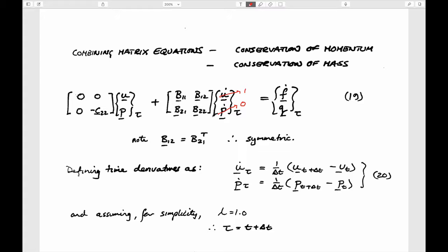And if you do that, then what that physically gives you is a reasonable interpretation of what these matrices are meaning in terms of process. And so the process would be that if this is unity and this is pressure, obviously these would be deformations within the system. So what we're going to do is apply deformations to this, and it's going to give us magnitudes of forces that have to be applied to resist those deformations.